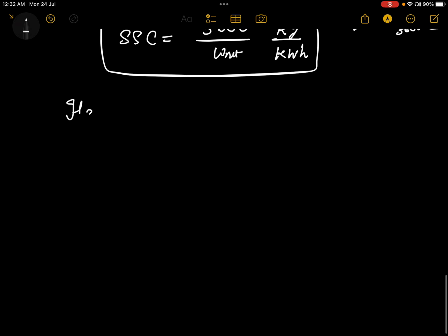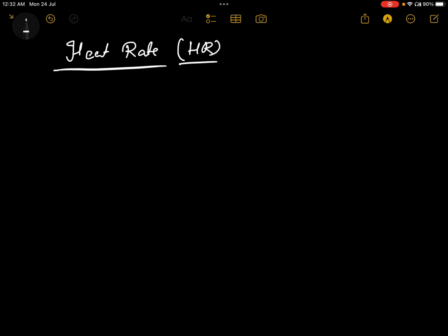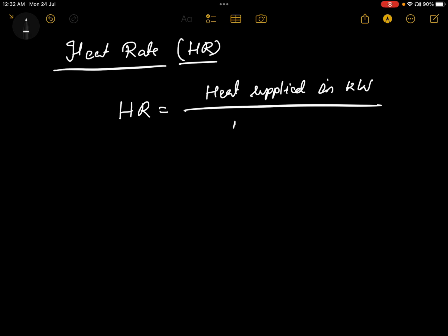Let's talk about the heat rate. What is heat rate, HR? Heat rate is the amount of heat input required for 1 kilowatt of power output. The name suggests it is the heat supplied in kilowatt divided by power in kilowatt.